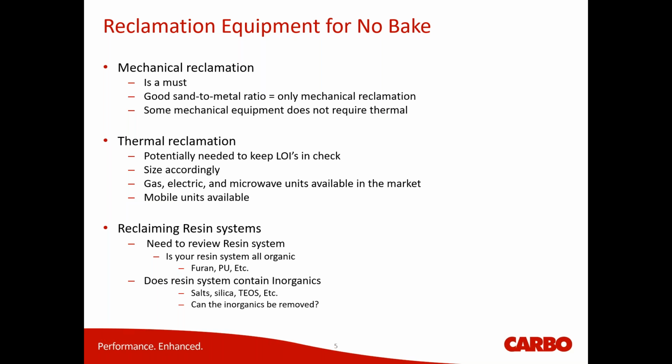First off, mechanical reclamation. In no bake, it is a must. You're getting stuff that's coated with resin and kind of bonded together. You need to break up those chunks before you get into any other reclamation.